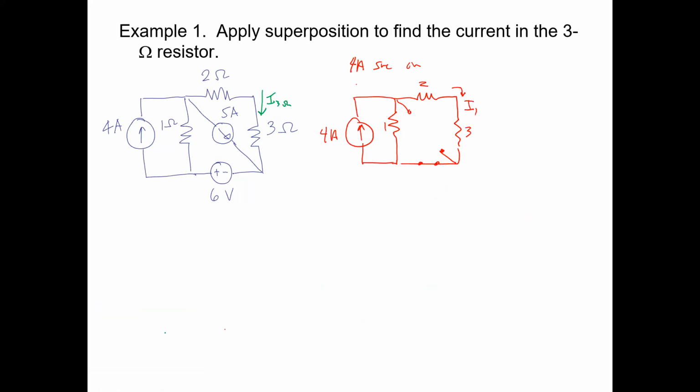And when you do that, what famous circuit type is being shown here that we can use to solve for I1? What type of circuit pattern is this? This is where it pays to kind of memorize those things. What is that? It's a current divider. And so you can use that current divider formula to easily find the current there, right? So the current is being divided through this resistive path, which is 5 ohms, and this resistive path, which is 1 ohm.